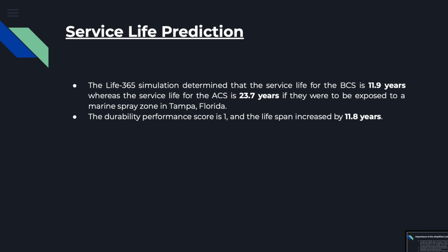The Life 365 simulation determined that the service life for the base case scenario is 11.9 years, whereas the service life for the alternative case scenario is 23.7 years. The durability performance score is 1, and the lifespan increased by 11.8 years.